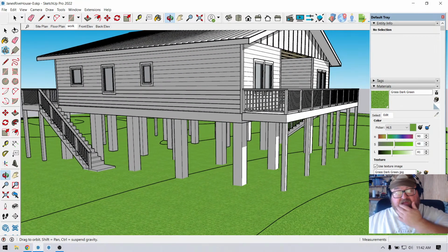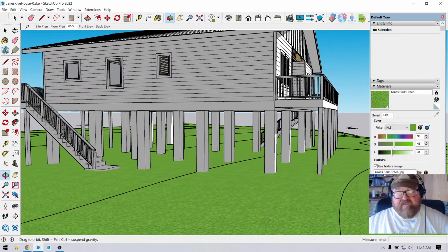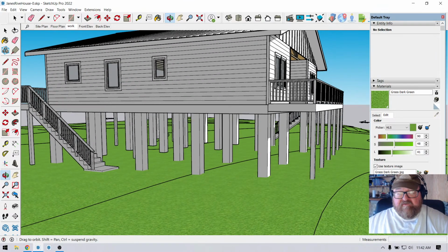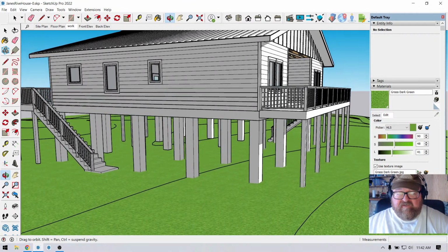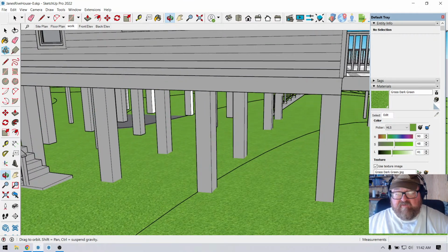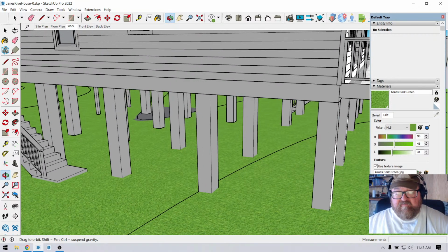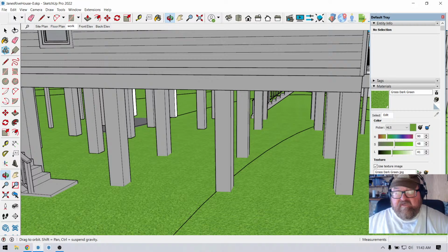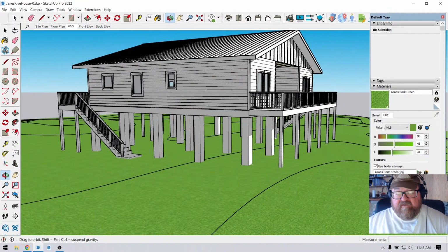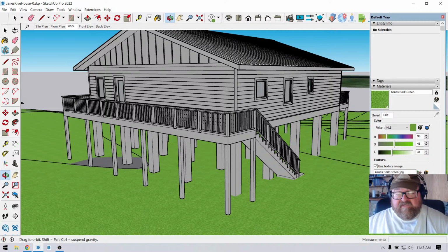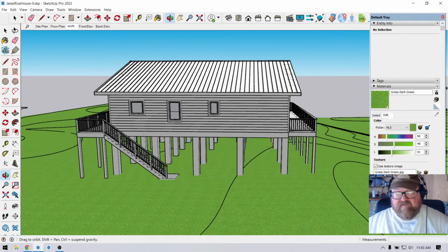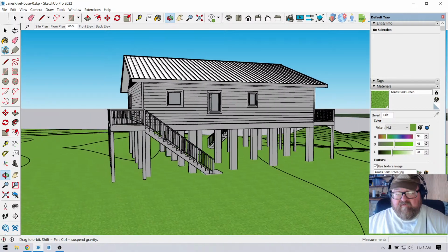I think what's probably going to end up happening is I talked to one contractor down there, and he says what they're doing is just laying up block piers, which I don't know. That's kind of cheesy for me, but what you do, it would be 16-inch block piers. You just lay two this way and two that way. You alternate them, and then they pour them full of concrete. Of course, they would have rebar in them also, and then they would have footings. I think what I would probably want to do is a strip footing all the way around to tie all the base ones together, because she's talking about maybe doing a slab, and that would also get the elevation level in there for her to put gravel in a slab under there.